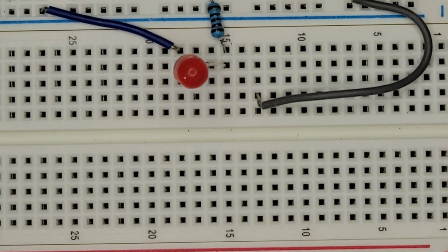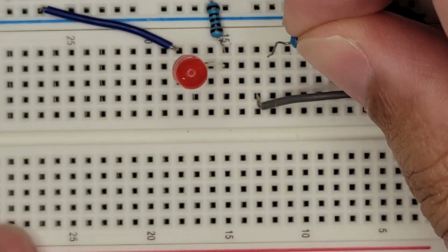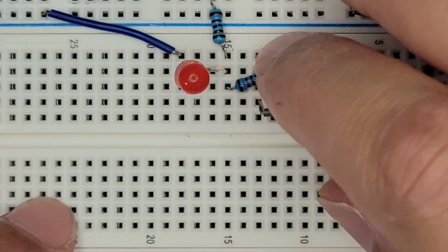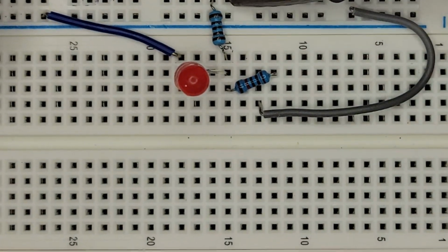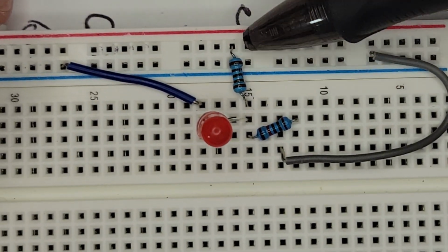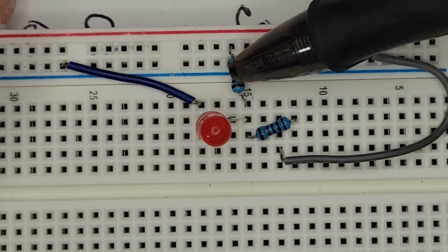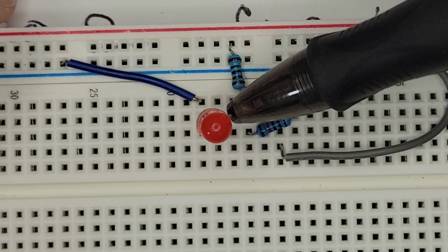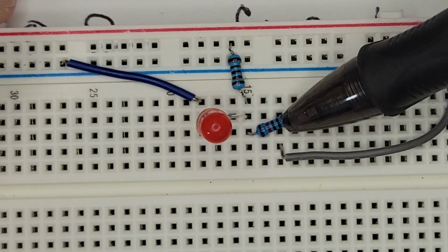So let's connect this 10,000 ohm resistor, which is a lot, and see if it turns back on our LED. So right now we have power coming through our main input, you could say, our pull-up resistor, I think it's called. And then it has a path to go through, either through the LED or through this other resistor.